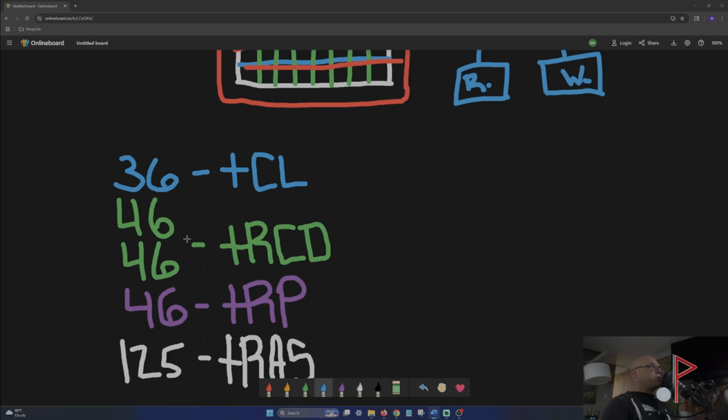And it's often two numbers for read and write, and they're usually the same. tRP is the time it takes to pre-charge the bit lines before opening another row. So it's how long the pre-charge process lasts before the memory controller issues a command to open a different row within that same bank. So that's your tRP, and then finally you have tRAS, which is just the time it takes between activating a row and the subsequent pre-charge.